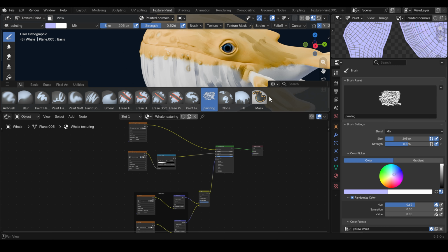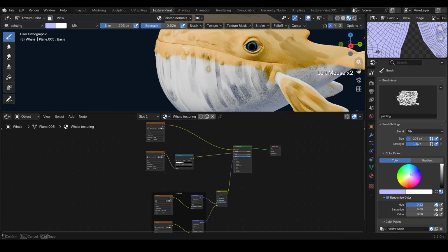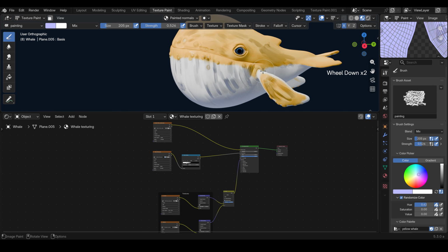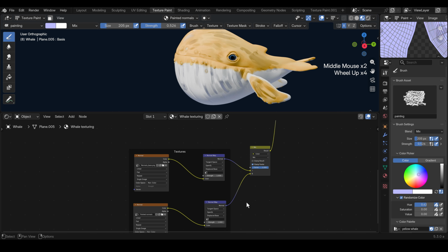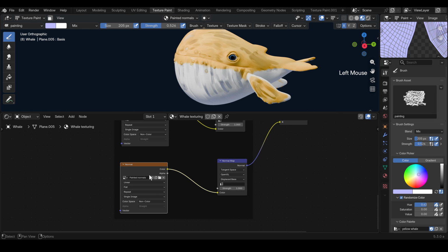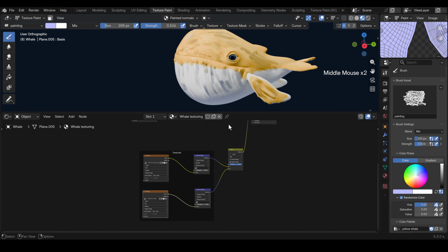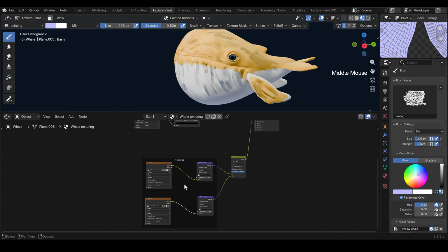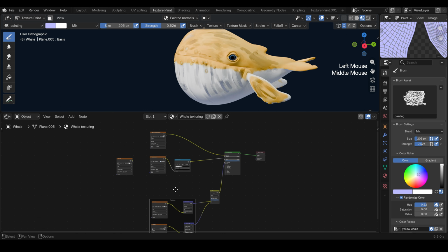So now let's make ourselves some more space. We can shrink the brushes for a moment and maybe this here, and then let's zoom out a little bit. And the first thing we're gonna do here is duplicating the painted normals node. Not like we really need a copy of it. We could just bring the connections from here, but since it's pretty far away, let's create a copy anyway to have it closer. Shift D. And then with this node selected, press Alt P, so you make sure to get it out of this frame here.